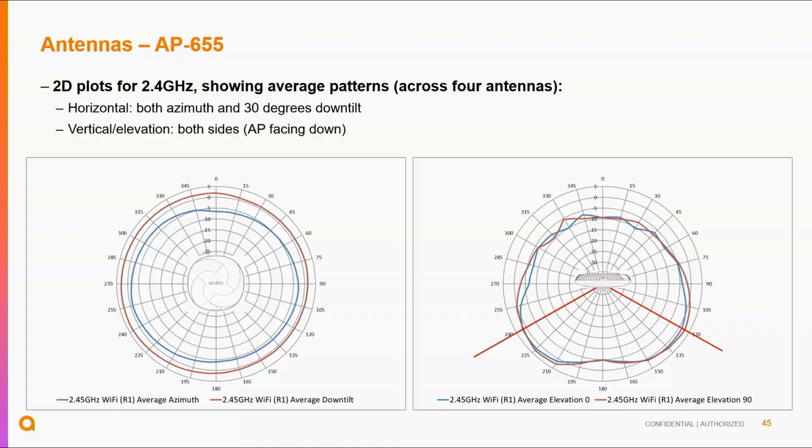The gain there is actually not as high as you would think it is. The maximum gain for these types of antennas is under an angle. We often describe it as a cone coming out of the AP, and you can see that here as well. The highest gain is not in this vertical direction, not in your ceiling, but under a down-tilt angle. So we document both, and that's a significant difference in the gain between those two patterns. All that means is that these antennas are really not perfectly optimized for maximum distance in a horizontal direction.